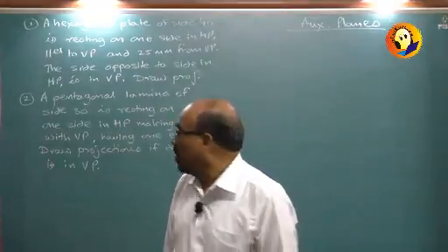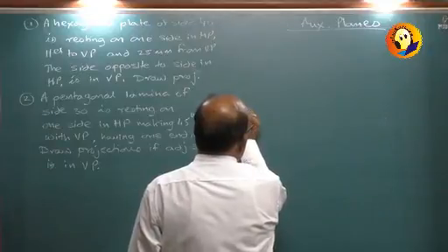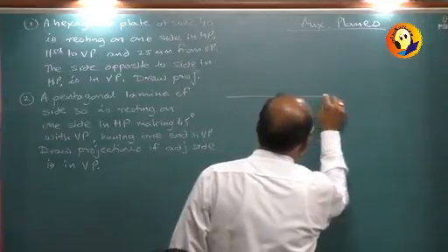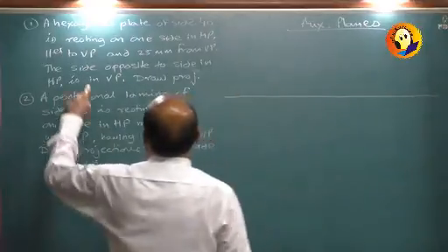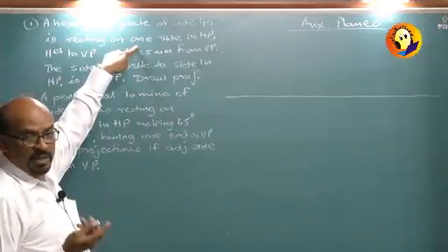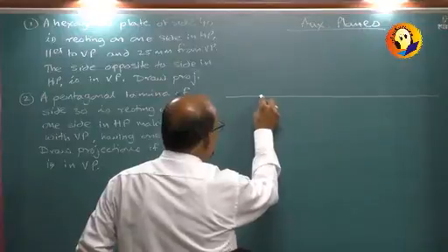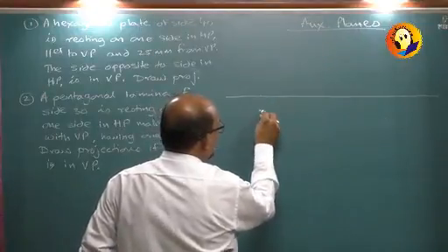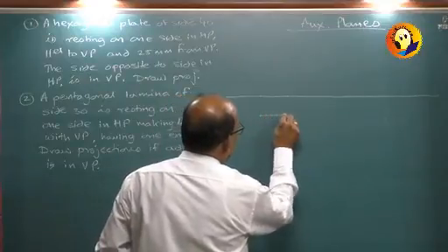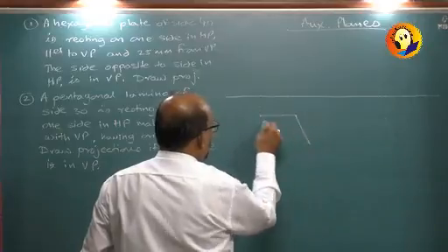right? So the initial orientation of the first problem is going to be, I'm going to draw it a bit smaller. If I am to keep this particular lamina, one side is in HP, I will have to keep it in HP only. But while drawing it, I will have to measure 25 millimeters, and then draw that hexagon with one side parallel to VP.